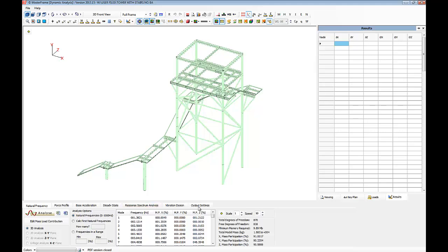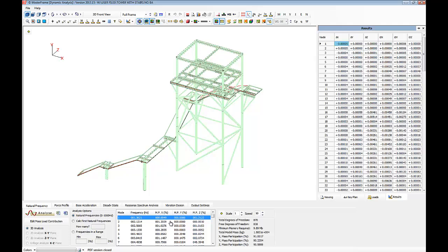So when you come into Dynamics, the first thing to note is the modal analysis tab. This is called the natural frequency tab. This is important. You need to have done a modal analysis before you can move on into any of the other sections. In this case, the model already has one performed on it, and you can tell that because the list of mode shapes is shown here. And you can click these and see the mode shape rendered on your screen.